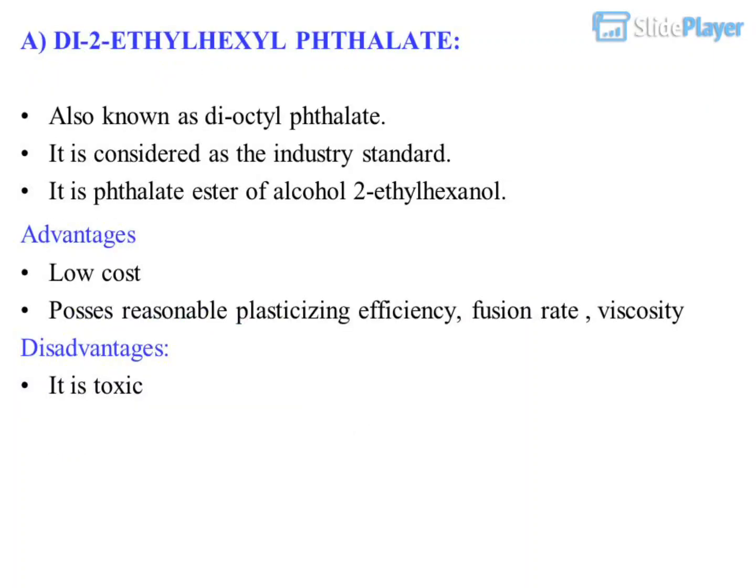Di-2-ethylhexyl phthalate. Also known as dioctyl phthalate. It is considered as the industry standard. It is a phthalate ester with the alcohol 2-ethylhexanol. Advantages. Low cost. Possesses reasonable plasticizing efficiency, fusion rate, viscosity. Disadvantages. It is toxic.